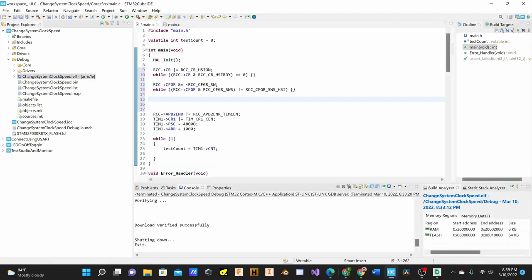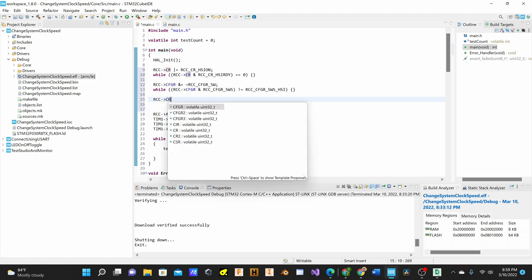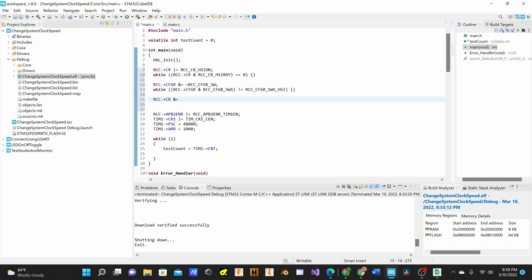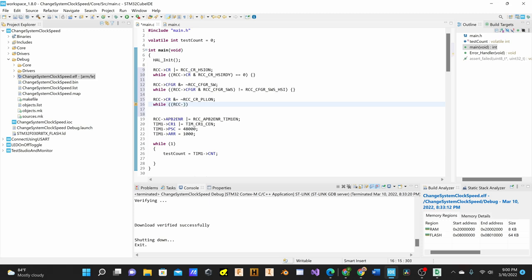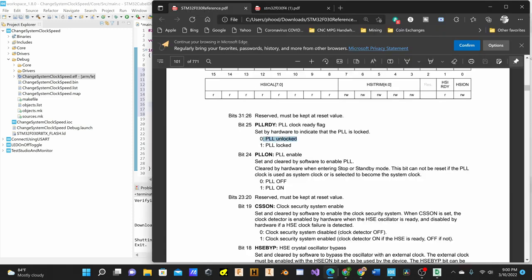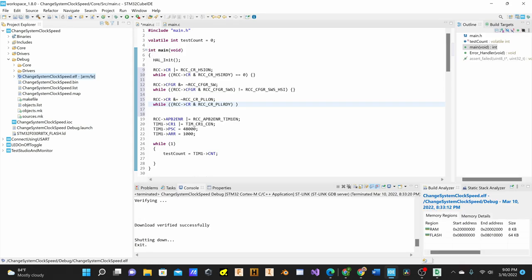So first thing we need to do is turn the PLL off. And that's in the RCC control register. We're going to use the AND NOT bitwise operation to set PLL on to 0, or off. We want this to be a 0, so we're doing the AND NOT bitwise operation. Now we're going to wait for the PLL ready to show us that it is unlocked. While it is, let's see, what number does it have to be? While it is not equal to 0, we stay in the loop because we want it to be 0. So let's go ahead and put in not equal to 0. I put these brackets in here because if I wanted some code to be in here, I can put it in here. These are demarcations for code within these brackets, just like the brackets with the int main, open and close, you have a bunch of code within it.